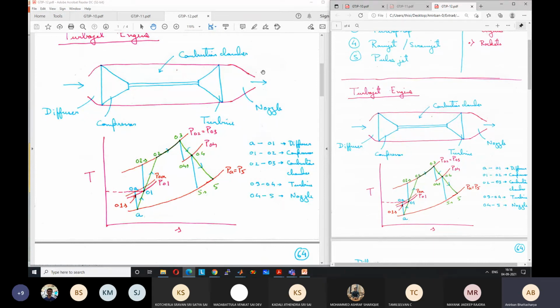Designing a convergent nozzle with variable cross-sectional area is much easier as compared to designing a convergent divergent nozzle. So only in very high-speed aircraft, like a ramjet or scramjet, does it make sense to use a convergent divergent nozzle. Otherwise, military aircraft operate with convergent nozzles only. So then, how is it possible to go supersonic with a convergent nozzle? Any answers?